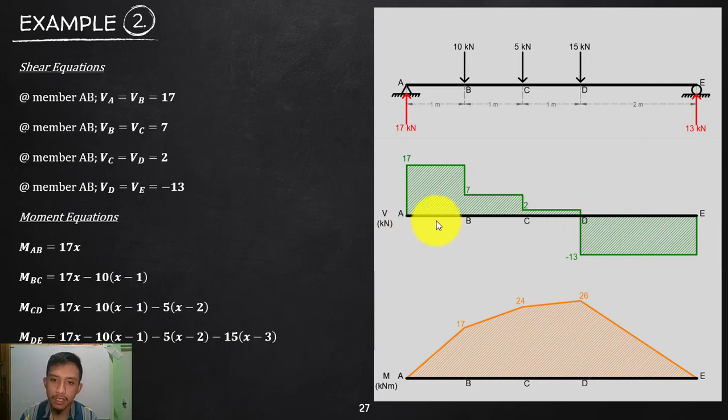So let's start with the shear diagram. So again, plot that one. So x and y, your horizontal is the distance. So actually drawing this is always best presented this manner, wherein you have your beam and the forces on top, and then below is the shear and moment diagram, so that if I want to consider, let's say this point, all I need to do is consider that section.